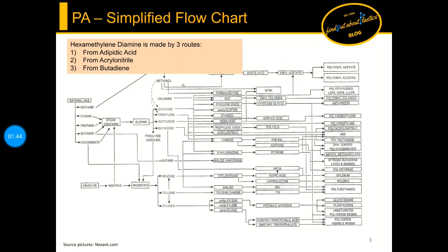Polyamide 6 is made by ring opening polymerization of epsilon-caprolactam, which is obtained over the benzene route. You can see here from benzene over cyclohexane to caprolactam. Cyclohexanone is first converted to its oxime. An oxime is a chemical compound with a carbon-nitrogen double bond. The word oxime is simply a combination of the words oxygen and amine. Treating the oxime with acid initiates the so-called Beckmann rearrangement to obtain caprolactam. Around 5 million tons is the global demand on caprolactam.